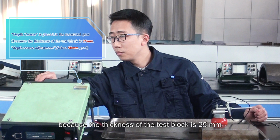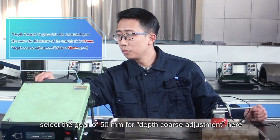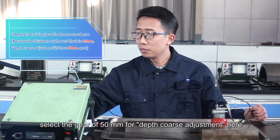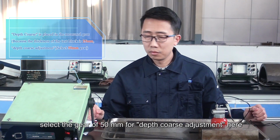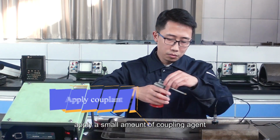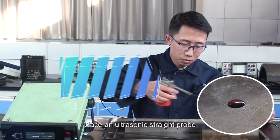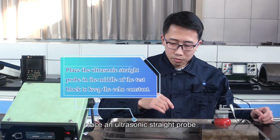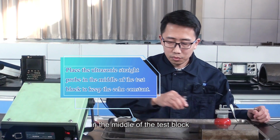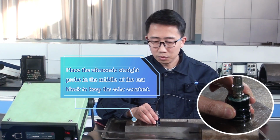Because the thickness of the test block is 25 mm, select the 50 mm gear for depth range adjustment here. Apply a small amount of coupling agent to the surface of the test block. Place an ultrasonic straight probe in the middle of the test block and keep the echo stable.